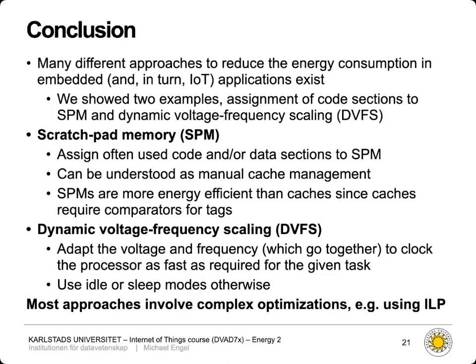We've seen SPMs as a component of the memory hierarchy that can often be used to assign code and data to it to save energy. And this could actually be understood as a cache management, which is not happening automatically, but it's happening manually. So your software decides either at compile time or in a more sophisticated way at runtime which parts of your program and so code and data to put in scratchpad memory, and for dynamic approach also which parts to evict at runtime in certain points and which to load from DRAM again into scratchpad memory.